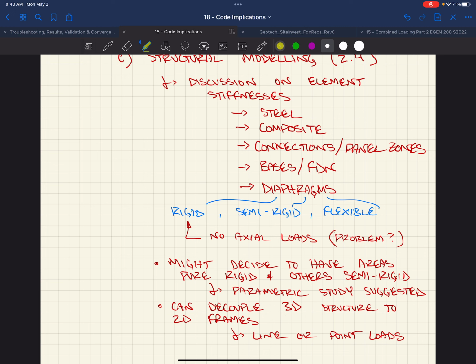Well, you look down here and you start reading about it, and they say, oh, hey, by the way, you're going to have the modulus of elasticity of the steel plus the moment of inertia of the steel member in negative, plus you're going to have the modulus of elasticity of steel plus this I lower bound. Everyone remember what the I lower bound was? Yeah, it's been a minute.